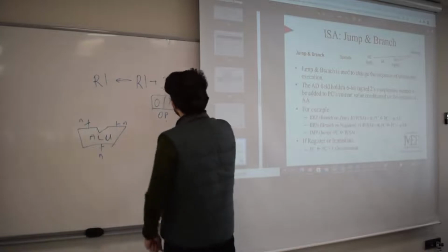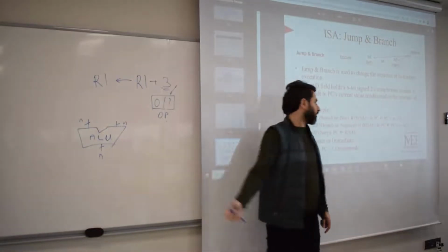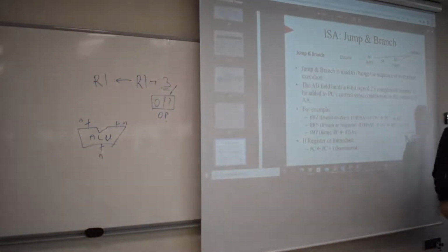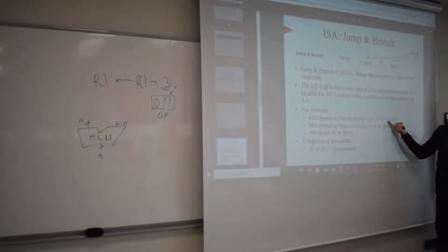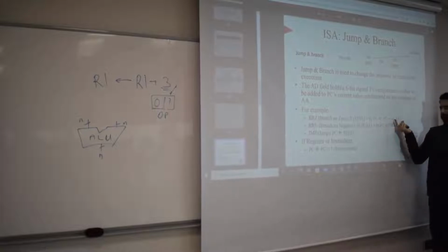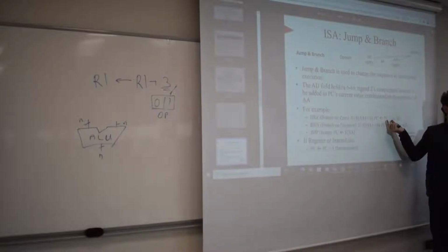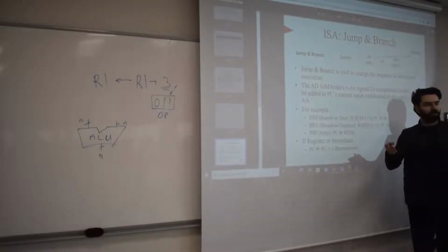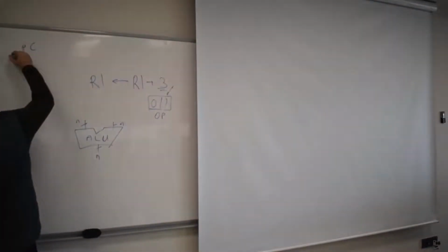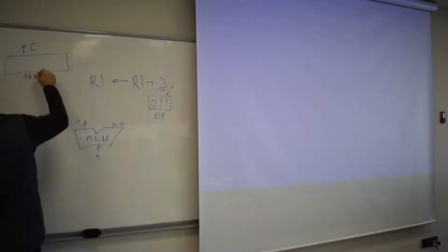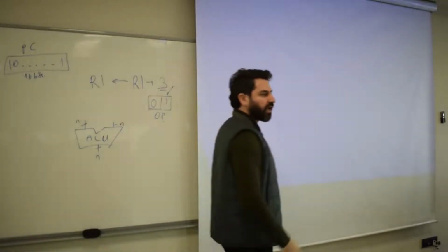However, this, for example, is not n-bits. So therefore, you have to extend it, okay? Since it's a 2's complement form of the decimal number, similarly here, we add a sign extension to get a 16-bit number, and then we add the program counter and this, okay? You see, there's a constraint that we all implicitly impose on our system. That program counter is 16 bits long. So what that means, that implies something, right? That implies if program counter is 16 bits long, okay, that actually puts a constraint on your memory size.